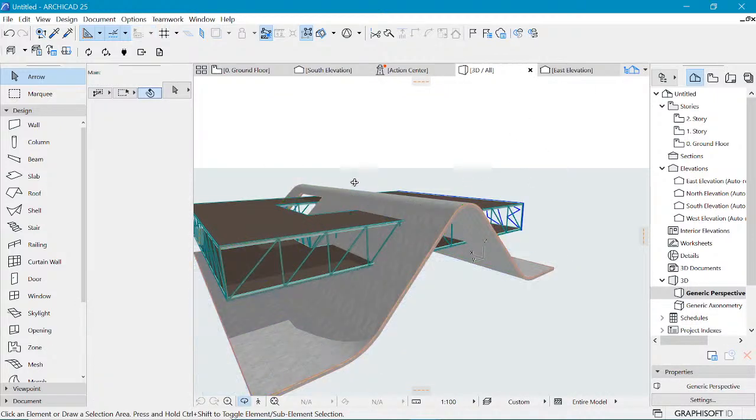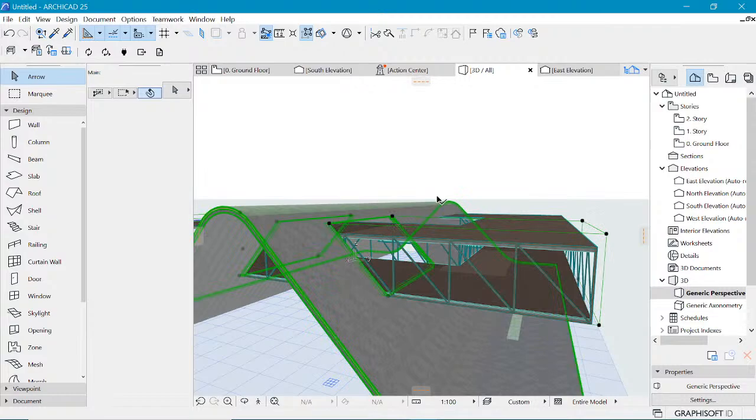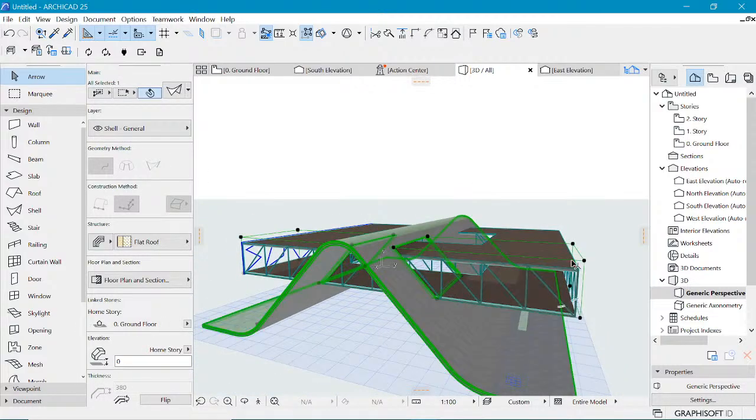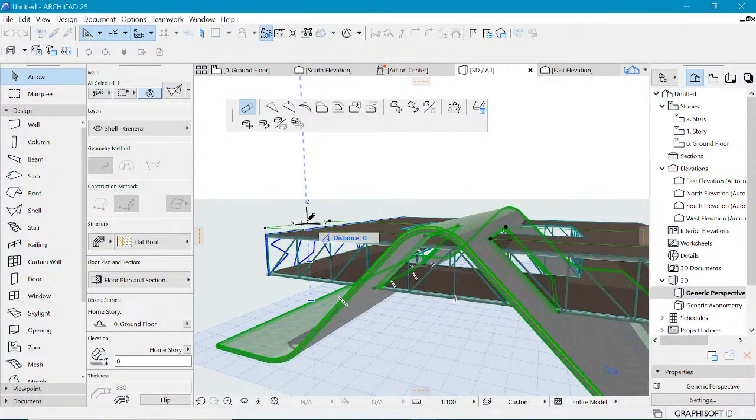And like I did mention before, you see it has been formed on this other side because that's where the elevation pointed us to. So we have it here, and like I mentioned before, automatically all elements that are in that elevation have been affected by this hole. But if we did not want to see that hole go through this other part of the shell, we could reduce that opening by clicking here and using the very first option, which is edit the extrusion length. We could edit the extrusion length of this actual thing and have it go down.